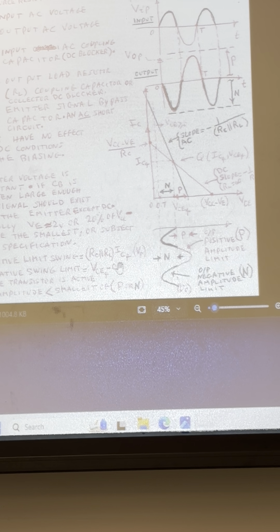So two quantities can be calculated: the P from biasing, and the RC and RL, and also the VCE choice you made initially. When I said VCE, IC will be given, I'm afraid nobody is going to give that to you if you're in an office. You've got to make your own choice to provide that amplitude swing.